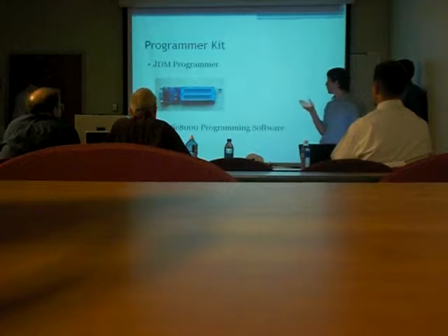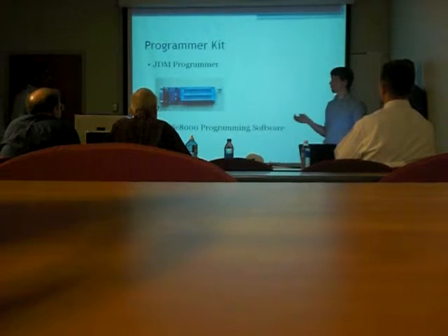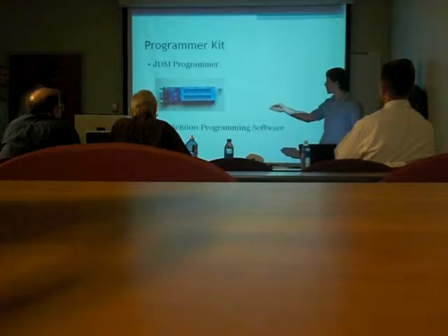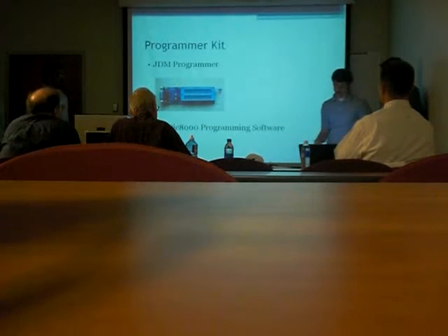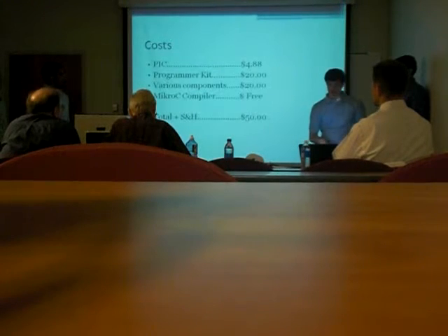For the programmer, I went with a simple JDM programmer, which works like this: when you compile the code, it outputs a hex file that represents all of the instructions, and you use a software called WinPic 800 that would load this onto the microcontroller. WinPic was a completely free program that's open source, available online.